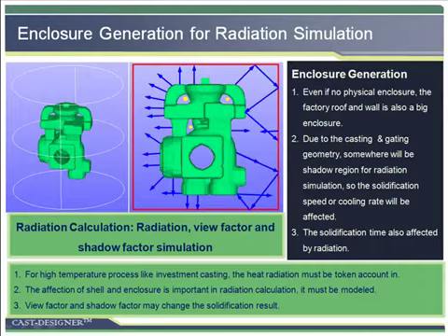Another important factor of investment casting is the view factor and enclosure generation. This is quite different from other casting processes. For a high-temperature process like investment casting, the heat radiation and the effect of the shell and enclosure must be taken into account. From experience and industrial validation, it is so important, and it must be well modeled.